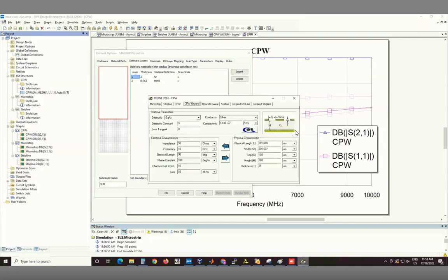So the CPW ground has a ground plane underneath the structure, which means you can now have capacitance between the top and the bottom plates. Whereas in this geometry, there's only capacitance between the lateral plates. Of course, the dielectric is still there, so field lines will penetrate, but there's no metal over there. So we saw this earlier that effectively, if you have a ground plane, there will be more capacitance per unit length. So for everything identical, you would expect the one with the ground plane to have lower impedance because the capacitance per unit length is higher.